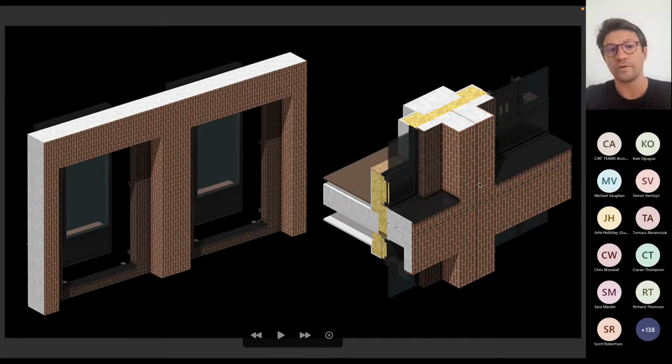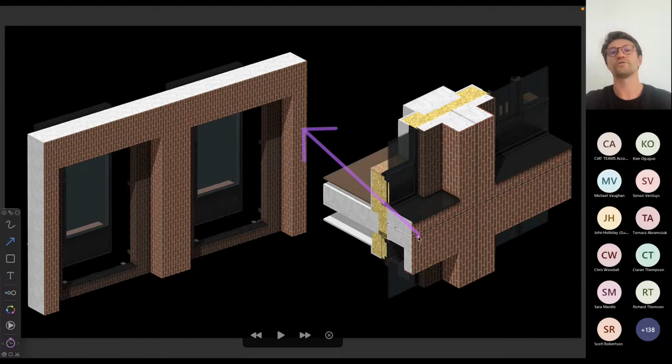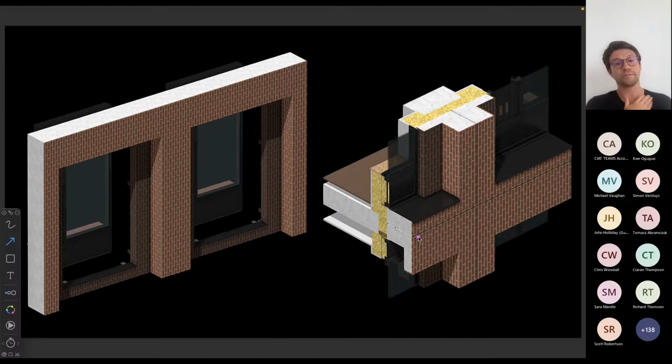So vertical stretcher bond would be prohibitively expensive if we are to achieve this protrusion in traditional masonry. In traditional masonry, the shelf angle out of stainless steel and the fire protection to deal with the hollow features here would be really expensive. And when we have a lot of geometry on the project, and a lot of complex brick patterns, it's really worth considering precast concrete as a facade.